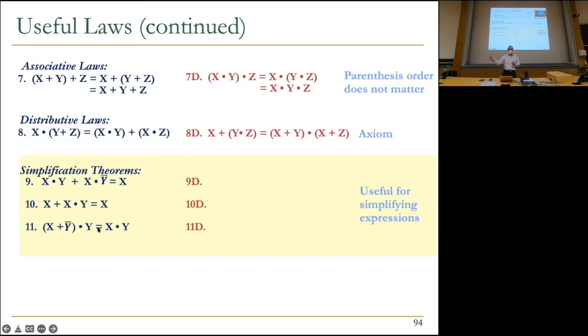So by doing Boolean algebra, you can simplify equations. So this is not a simple equation, basically. You can see that at some point you have a logic gate or a function that looks like this. You can realize that, oh, I don't need to implement logic gates like AND or another AND and a complement. I just have X, right? That's the idea, basically. That's the reason this makes sense to study in digital design, because everything is based on Boolean equations and you can simplify things.